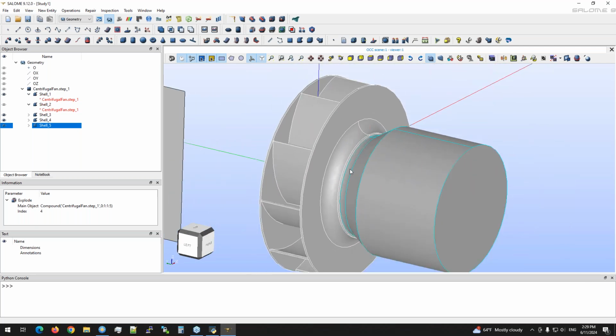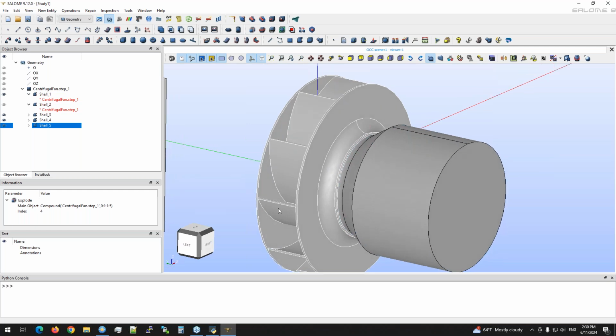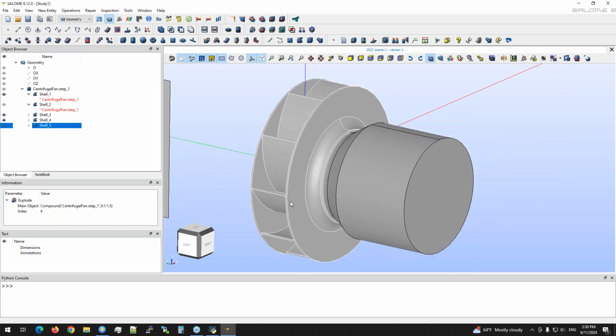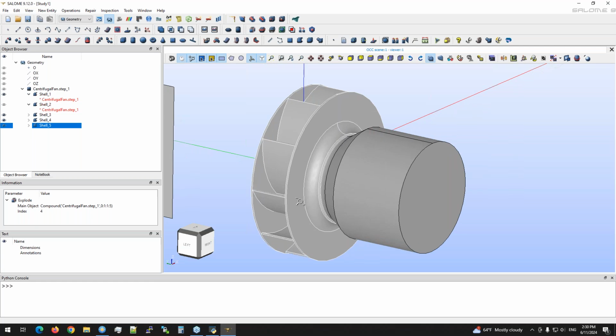So first, how to create a rotational domain. So typically we need to create or define the domain which includes all the rotating parts, or at least all rotating parts which are not rotationally symmetrical, which do not have the symmetry, because all these rotating parts have to be included into the rotating part to properly treat all the rotating effects within the simulation model.